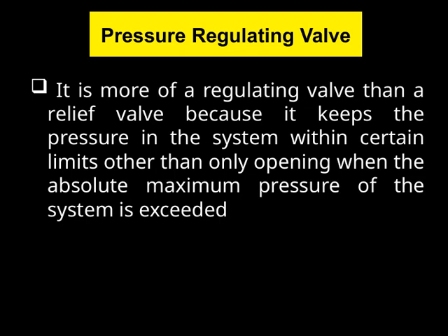So, what we're looking at here is actually more of a regulating valve than a relief valve. The key difference is that a regulating valve works to keep the system pressure within a certain range, rather than just opening only when the absolute maximum pressure is exceeded. It's designed to maintain a steady pressure level, ensuring the system operates smoothly and safely.